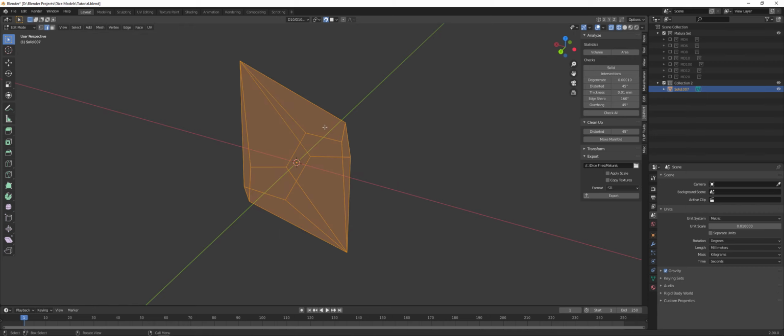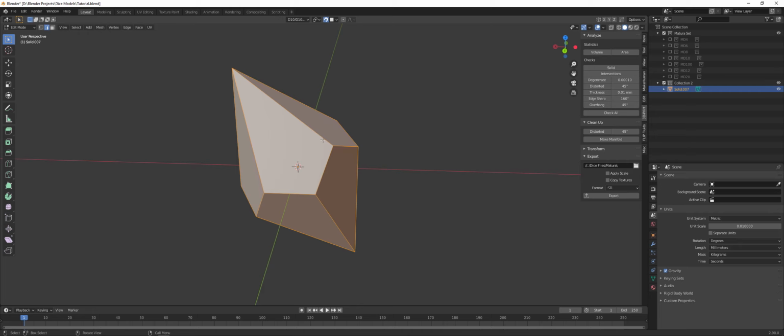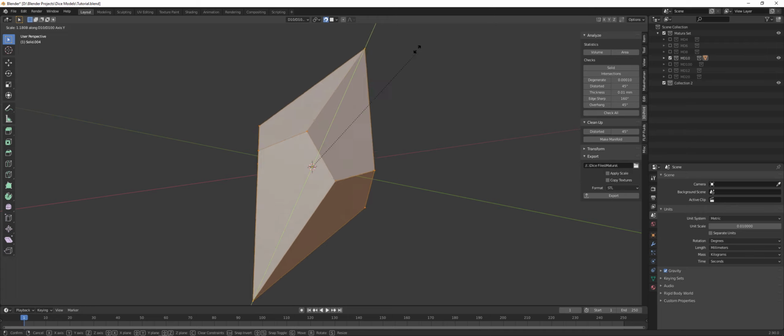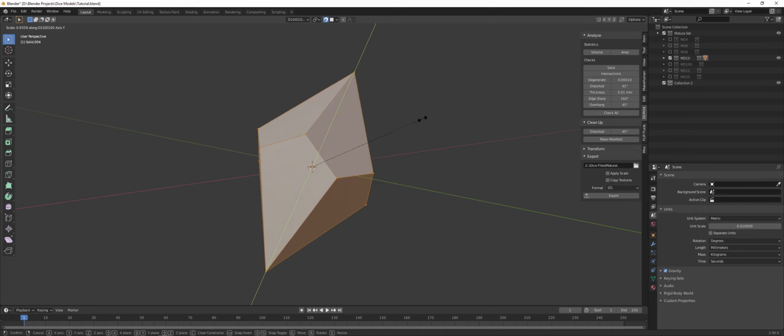You then select all, and in edit mode, you can scale along that Y axis, and you will be able to make a chunkier or a pointier D10. It's really simple, it won't affect your numbering, so don't worry about that. And you can choose how much you want. I suggest you either leave it intact, which will have the same angles here as the D12, and I find that quite pleasing, or you scale along that axis by a certain amount.